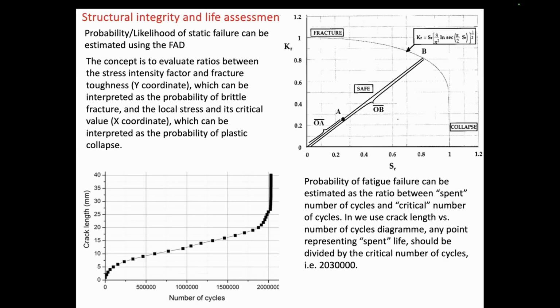Those are simple values, linear elasticity, but it also concerns the eventual plastic collapse, because if net stress reaches critical stress, then we go into plasticity. And this is the limit curve. So if the point that you calculate is here, it is safe, of course, if you did it in a conservative way.